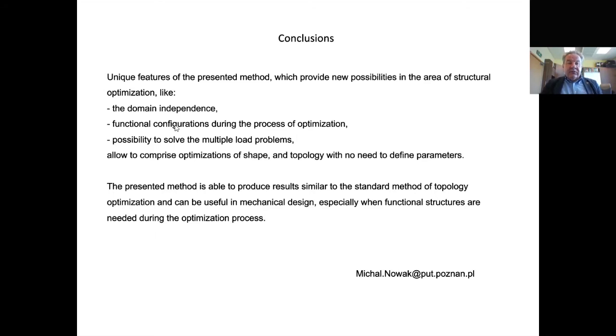Then there is a functional configuration during the process of optimization, which means that there is no fictitious material. So there is no problem with filtering, or with the decision whether a density of material should be treated as real material or as a void, because we still have the definition of the real material.